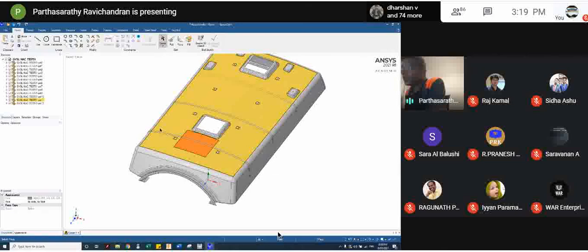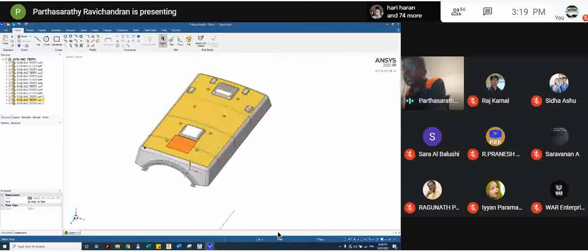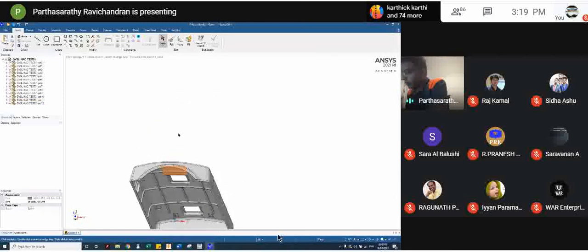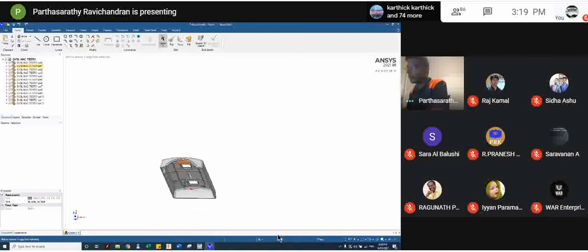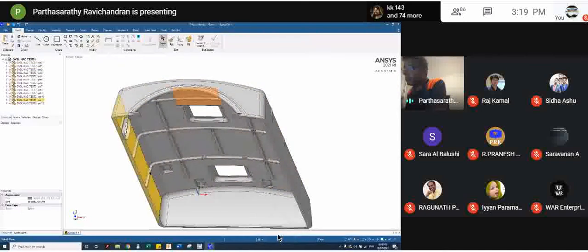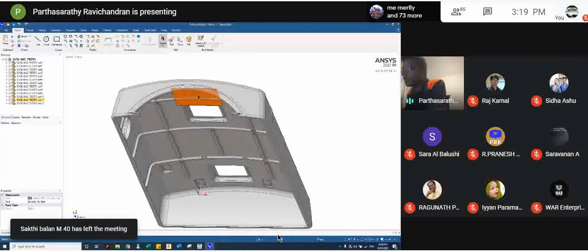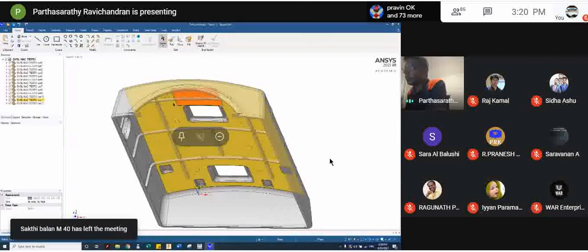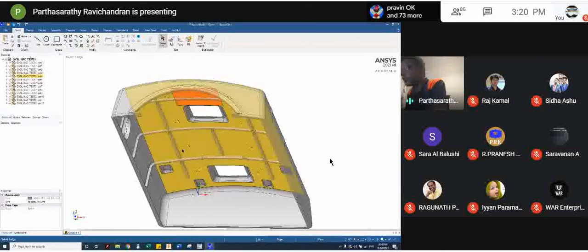As far as nacelle covers are concerned, the major factor is not the stress, unlike in an offshore wind farm where the criticality is more. On onshore wind farms, deformation is the main result that is viewed. So if you look at the bottom side, this is how we place the stiffener ribs, and it didn't play a major role. Where the window was, we still had a stiffener there instead of in this location. We just shifted it, and the deformation started to change its location.